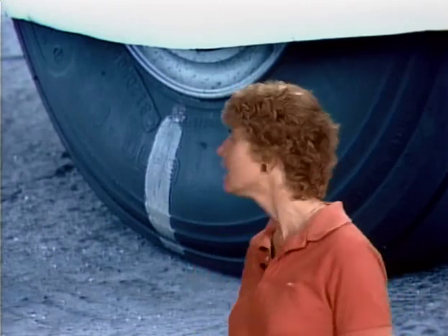Now, what about tire maintenance for a private pilot? A private pilot is allowed to remove, reinstall, and repair landing gear tires if he owns and operates the aircraft. It has to be his own aircraft. He's not allowed to do it on someone else's. And if he's doing it on an aircraft that he owns and he operates, not one that somebody else operates, that is considered to be preventive maintenance. So a private pilot can remove, install, repair his own landing gear tires on his own aircraft that he operates. He can do it, and it is considered to be preventive maintenance.